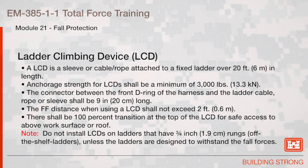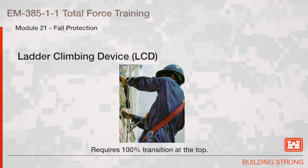Note: do not install ladder climbing devices on ladders that have 3/4 inch rungs, off-the-shelf ladders, unless the ladders are designed to withstand the fall forces. This is an example of a ladder climbing device that uses a cable and it's attached to a fixed ladder. It requires a 100% transition at the top.